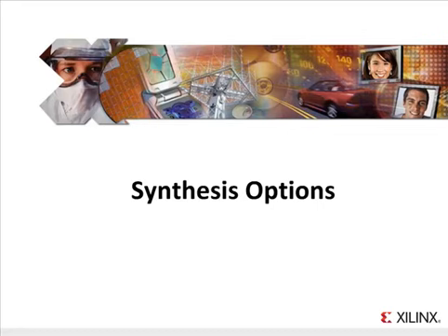This module introduces many of the synthesis options that are available in the latest FPGA synthesis tools, including Xilinx's own XST. This module introduces the primary synthesis options and the concepts behind their usage. These synthesis options can have significant impact on the quality of results a designer will get when synthesizing for an FPGA. This module also provides some detailed introduction to the specific options included with XST. These synthesis options will impact the speed of your design and help you manage your FPGA resources.